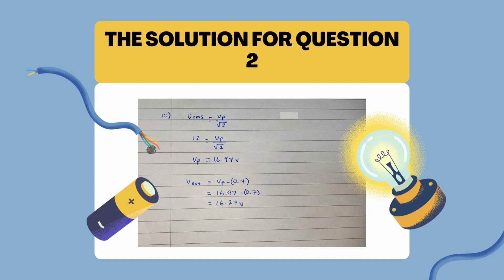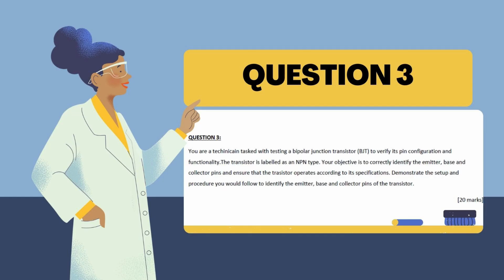So now we can calculate the output voltage using the formula VP minus 0.7. So the VP is 16.97 minus 0.7, and we got 16.27 volts for the output voltage. So now we will continue with question number 3.